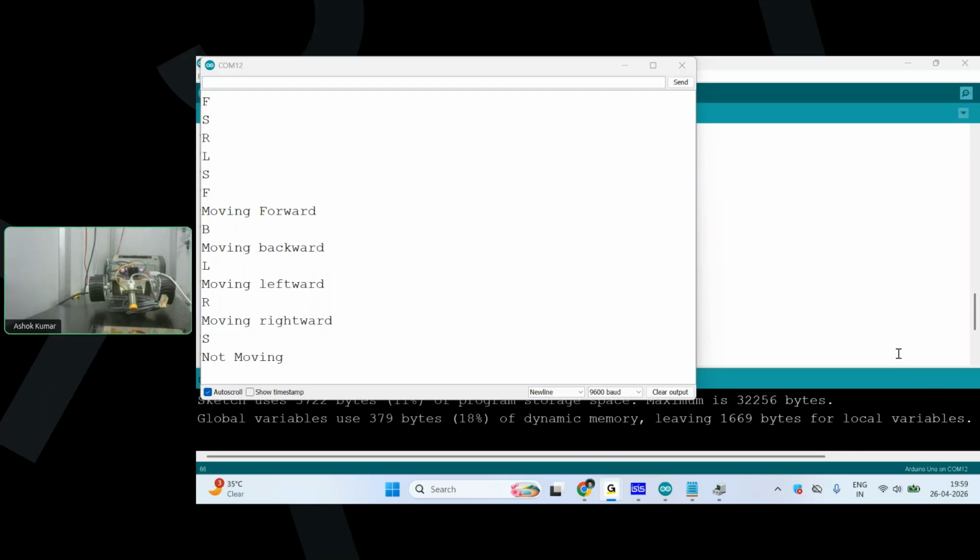And one more option you have. Because you know this Uno board which I have is a DIP board, where you can remove the IC. Let me show you. I have another board also. See, this is called a DIP board. So you can remove this IC. Because you don't want to use the whole board, remove this IC, and connect the IC which you want to program. It should be the same ATmega328P. Connect the same IC here, use this USB cable and program it simply.